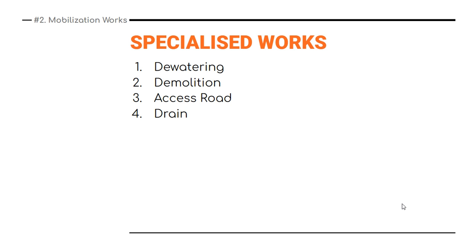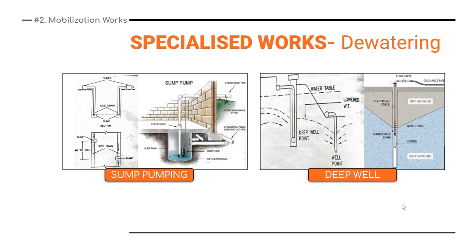It's non-mandatory though, but let's learn how these works are conducted, because it's quite important, because you may face it anytime, anywhere, in any kind of complex site conditions. Yes, we'll understand the conditions as well. So the first method for dewatering is sump pumping and deep well. These are the basic two methods of dewatering. But let's understand the site conditions where each is employed.